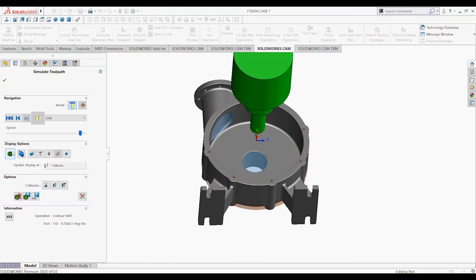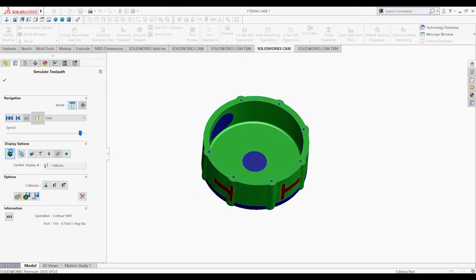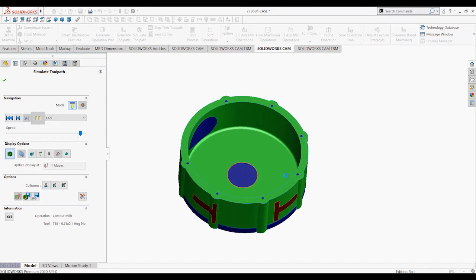Let's go ahead and press this Show Difference button so that we can display the difference between the machined features and the target part. So as you can see here, this area of the circular pocket is all appearing in green. And that means that it has cut to zero tolerance. So if you see on the top left corner, areas of red indicate overcut areas, and areas of blue indicate undercut areas. So based on the strategies I've applied, we look like we're good, and this circular pocket would be cut to spec.